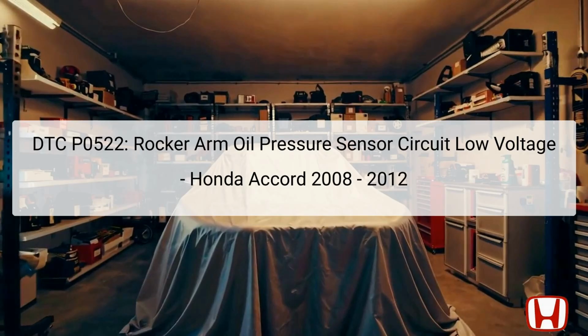Located near the cylinder head, the rocker arm oil pressure sensor monitors the oil pressure and transmits this data to the engine control module, ECM, or powertrain control module, PCM, for real-time adjustments. When there's low voltage detected from this sensor, it can trigger the check engine light and may lead to decreased engine performance. Before any troubleshooting begins, it's crucial to record all freeze data and any onboard snapshots to gather a complete picture of the vehicle's current condition. This initial step will help in diagnosing the root cause effectively.